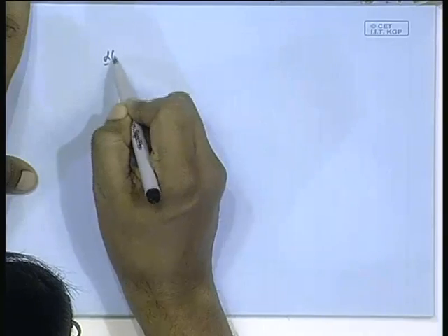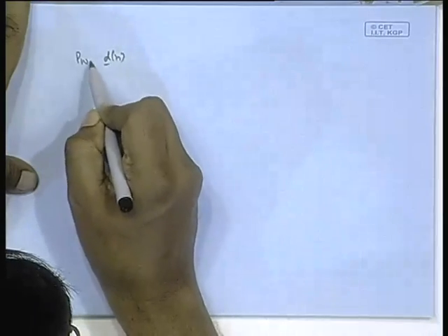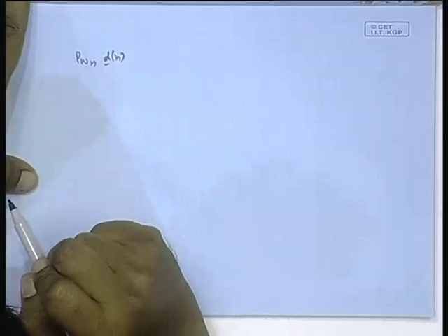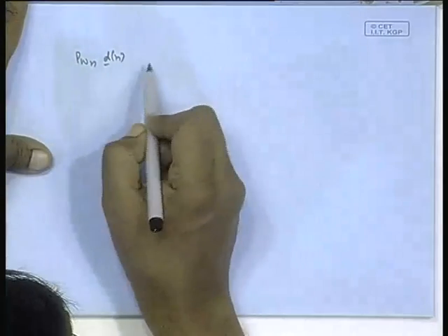Now, suppose up to index n equal to n naught, from n equal to 0 to some index n equal to n naught, system input statistics or Dn statistics, they are fine, they are constant. At n equal to n naught, suddenly there is a jump, the statistics changes, R matrix changes, P vector changes. The point is, if you are immediately in the vicinity of n naught, n naught plus 1, n naught plus 2, if you are standing around that zone, then what is the sum of squares? Suppose you are minimizing this, you are projecting Dn on this Wn, isn't it? You are doing this projection.